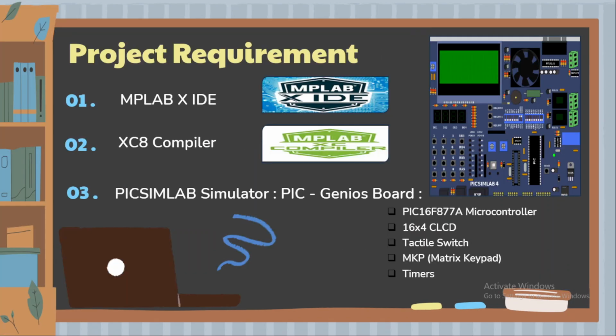To implement this project, we require MPLAB X IDE for coding, XC8 for compiling code, and PICSimLab to simulate hardware. In the PICSimLab simulator, we use the PICGenius board, especially the PIC16F877A microcontroller, CLCD, tactile switches, and matrix keypad, timer, interrupts, and so on.